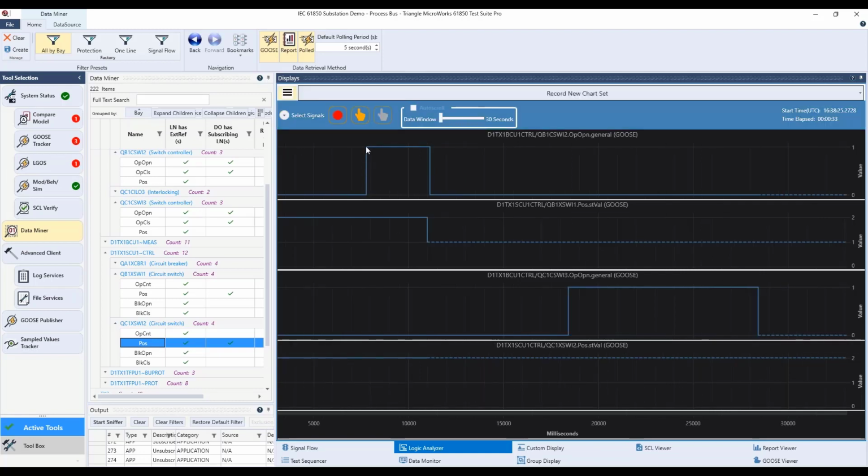So we see here the first operation of the busbar disconnector, we had the op open. After a while, the position changed from on to off. So far, so good. Then we tried the other one, and here we never got the position change. And that's why at a certain moment, we had a timeout. Every control operation has a timeout, so when we got the timeout, it aborted. So apparently, the signals that we send out from our BCU seem to be correct, but there seems to be something in the SCU.